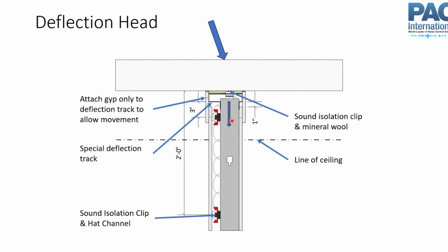So all of these different details. There's a lot of different moving pieces and details to pay attention to here, both for acoustics but also for fire, constructability, and your deflection. So a lot of different details to pay attention to. And if you just think about those, cavity path and structural path, tracing those things with your pencil or your mouse, it'll help out with a lot of these details.